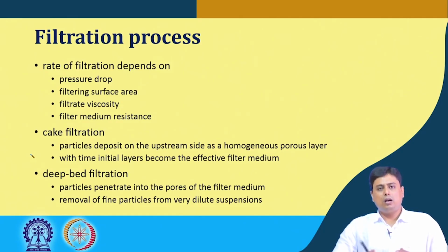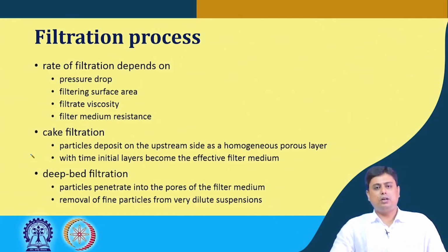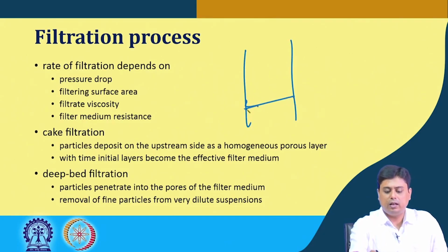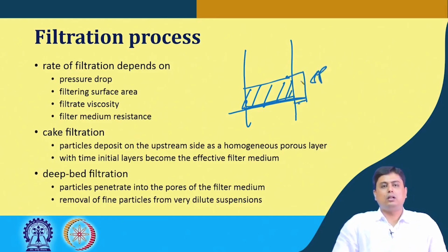So this effective pressure drop, or the whole pressure drop that is required, actually dictates the rate of filtration. Or even if you can think of having, if this is my filter and its support, and if this is the cake, so basically this pressure drop is what is important in this, or dictates this rate of filtration in this case.